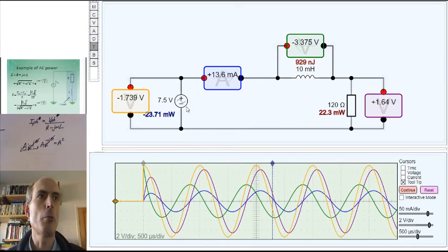For most of the operation of this circuit, the voltage source is pushing energy into the circuit, and certainly on average, the voltage source is pushing energy into the circuit, but at these particular moments in time, the voltage source is absorbing energy. This can be a bit of a problem. For certain types of alternating voltage source, they're fine at giving out energy. They're not particularly good at taking energy back in and storing it at certain types of the cycle. It can cause problems in power networks.